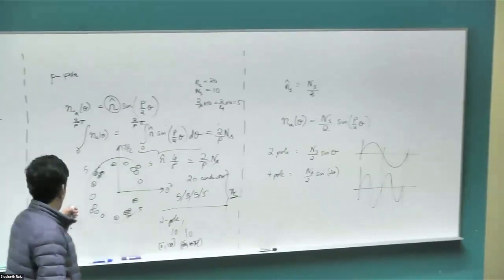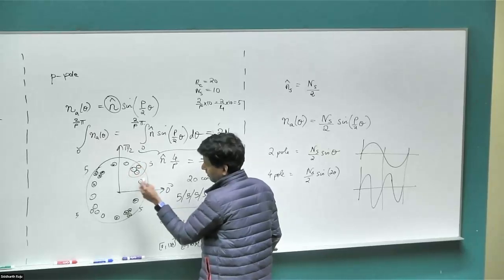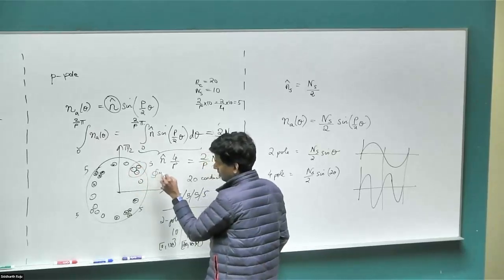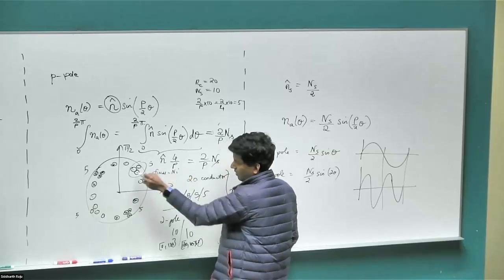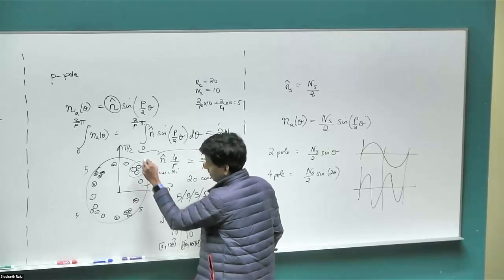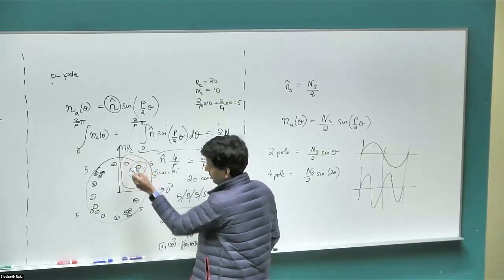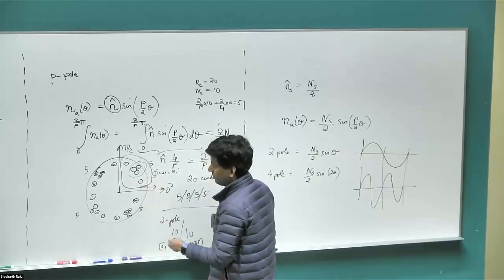So for instance, let's say we are doing it for this 4-pole motor. We would have taken this tiny loop, it would have given us integral H dot dl equal to some Ni. We know the N here, and we know the current is just I for all of them. And then we'll take another loop, and then another loop until we get all the loops within the coil, and that will be the point where the H field is maximum.